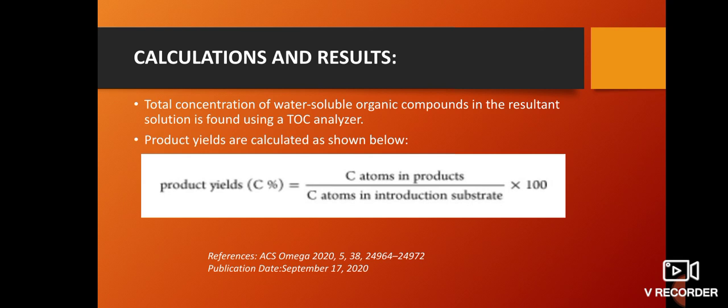In conclusion, this study investigated the relations between the adsorption properties and the catalytic activities of the sulfonated activated carbon catalyst compared with Amberlyst resin catalyst. From the comparison of reaction rates in this study, Amberlyst 70 with large amounts of high sulfonic acid functional groups is suitable for hydrolysis of polysaccharides with DP 3 or less. The sulfonated carbon catalysts are suitable for hydrolysis of saccharides with DP 5 or higher. DP is degree of polymerization.